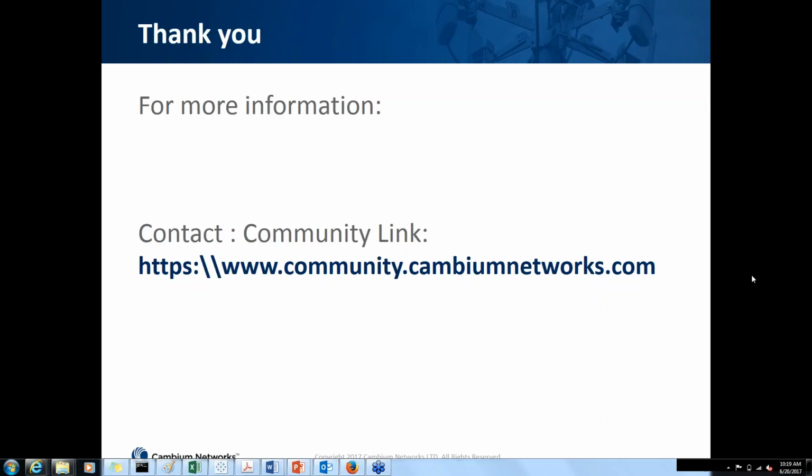There's also a question: is there a cost associated with using the radio in a PMP or HCMP mode in terms of option keys? Yes, you will need to buy an HCMP license key for the master node in the diagram to be used in HCMP mode. You don't need it for the remote nodes.